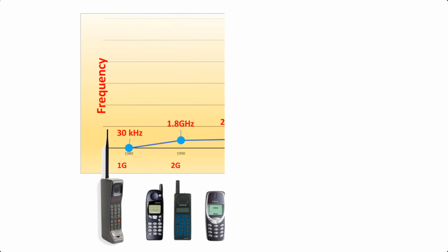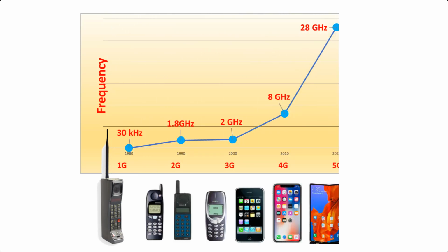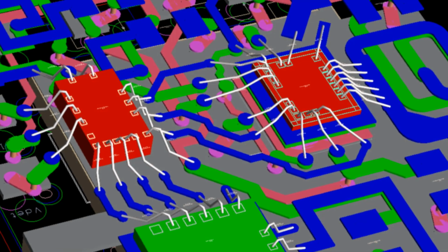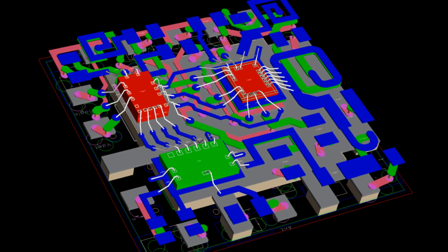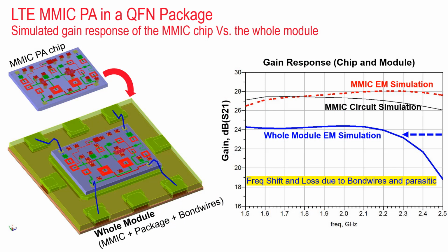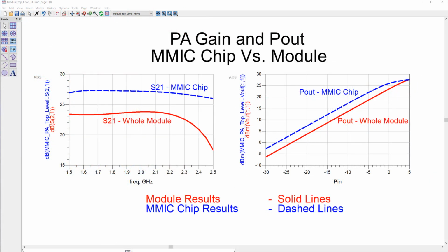As the RF industry trend continues toward higher integration densities and frequencies in 5G, defense aerospace, and IoT applications, the need for highly integrated multi-technology RF modules grows. However, designing an RF module is challenging because the parasitic effects of physical interconnects tend to cause frequency shifts, which must be accounted for by using a combination of electromagnetic and circuit simulations.